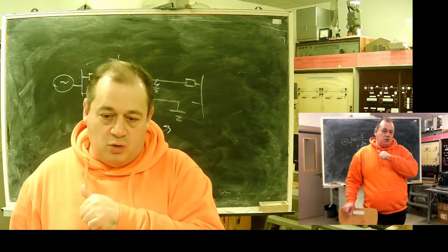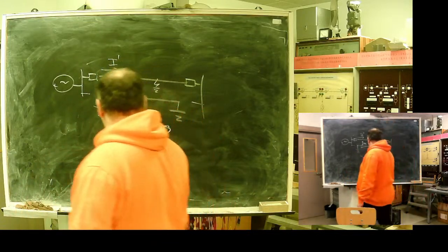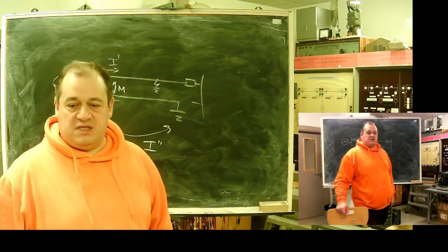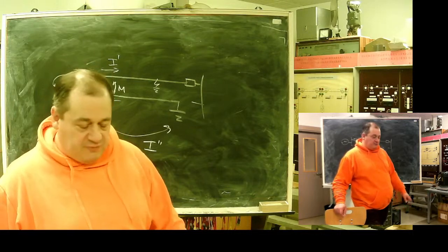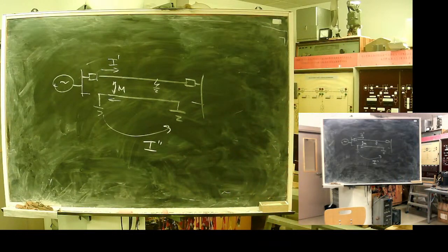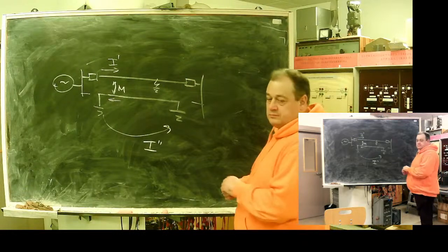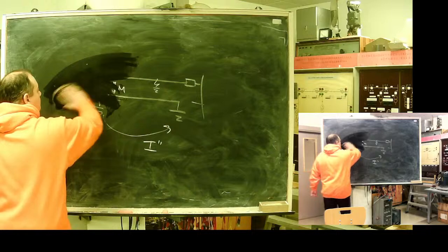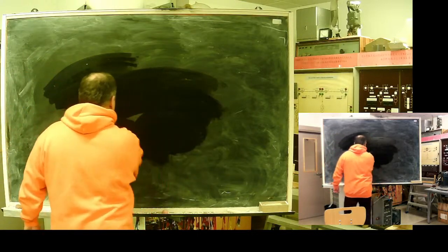In case the line is disconnected for repair, and earthed on both ends, you need to change settings of your distance protection. It's mandatory, or it will fail.